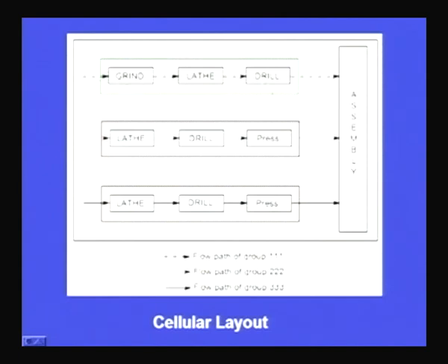because there is a logical sequence of operations. The raw material is coming from here, getting processed, and then finally a sub assembly is ready here. So this is having all the advantages of a product type of layout. And similarly, in process type of layout, we have dedicated sections for the different processes. Within the machining shop, we may have a drilling section, a shaping section, a turning section, different types of sections within the machining center. So dedicated shops are there for each and every type of operation. That is the advantage of a process type of layout.